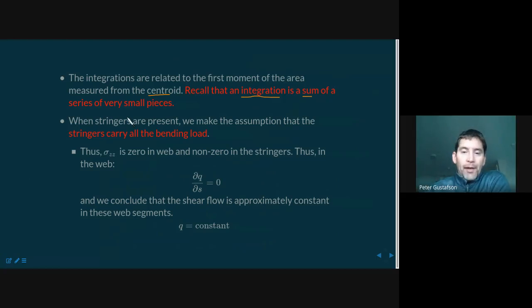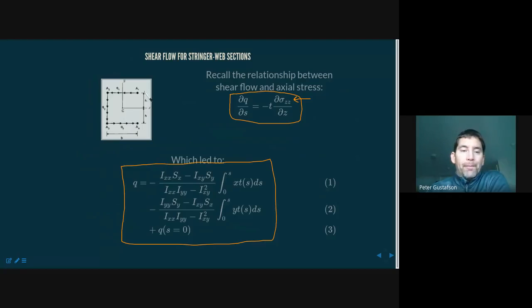Now, the next statement, let me go back to this image for a minute. Okay, again, what do we have? We have these reinforced structures, so we've got big concentrated areas here. And then we have thin-walled structures. Keep in mind that thin-walled structures tend to buckle. They can't carry compressive load very well, for one thing. And that's part of the reason why we reinforce these.